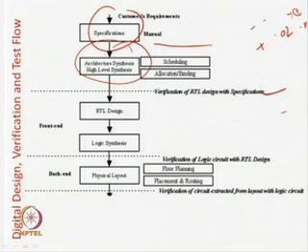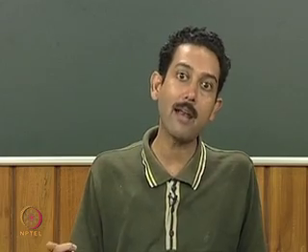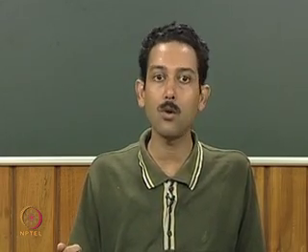So, what do we mean by RTL design? That is register transfer level design. In this case, we say adder, then we say registers, then multipliers, then we set a clock. In the RTL design, what type of adder do you want to use? Do you want a ripple carry adder? Do you want a carry save adder? Do you want a carry look ahead adder? Those things we decide. Also we decide registers.